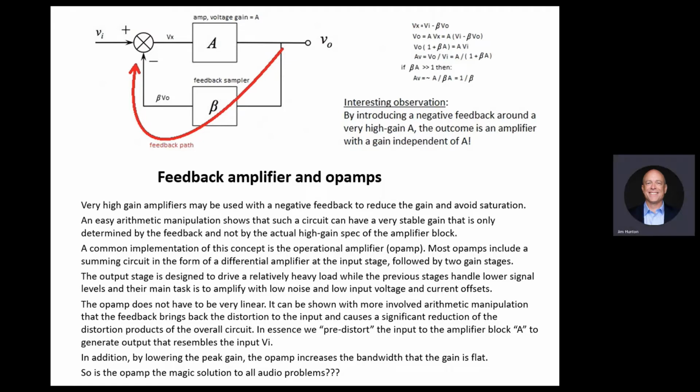With those formulas here, they say the signal is coming back with no delay, essentially, right? Because we're saying Vx is Vi minus beta Vo. No, it is minus beta Vo. However, Vo is not Vi times A, like in the next formula. It's really the delayed input signal times A. Okay, you bring it back with some delay, now you have a phase differential.